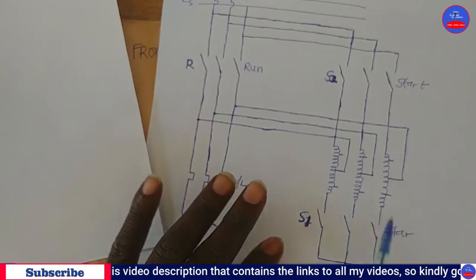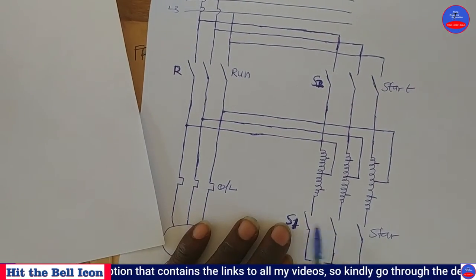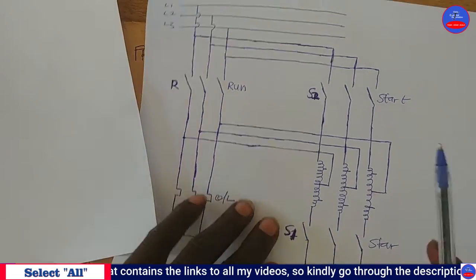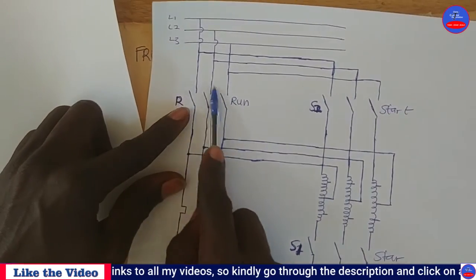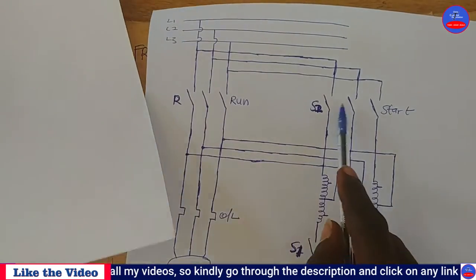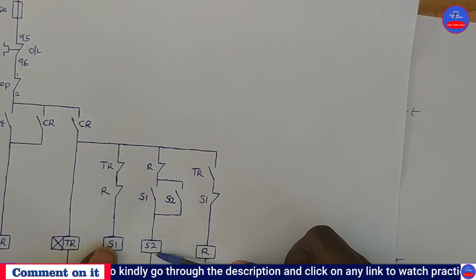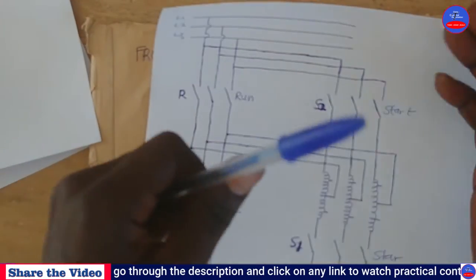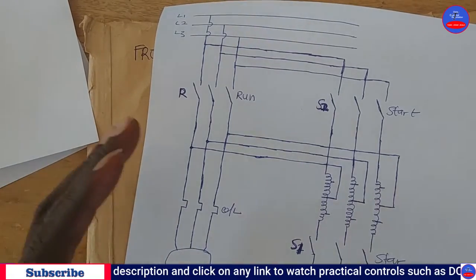So it means that when the timer finishes counting, this S1 is going to open, and then, following that, when this one opens, this side will close. When this side closes, it will de-energize the S2 contactor through this relay. So there will be some time for the motor to operate. So this is a closed transition type.